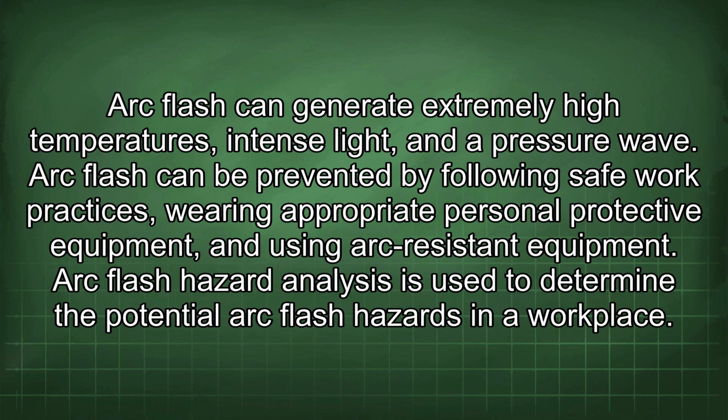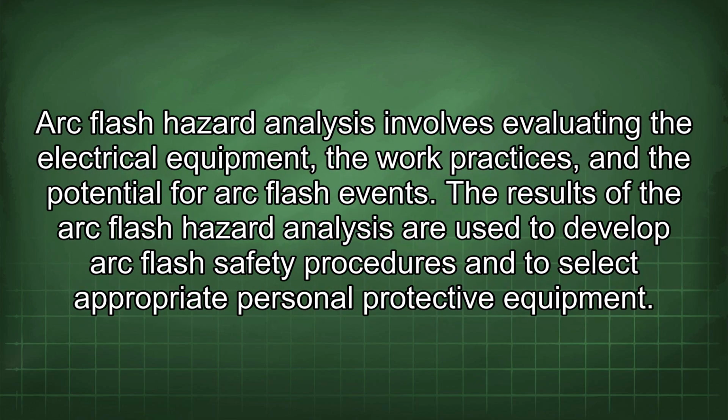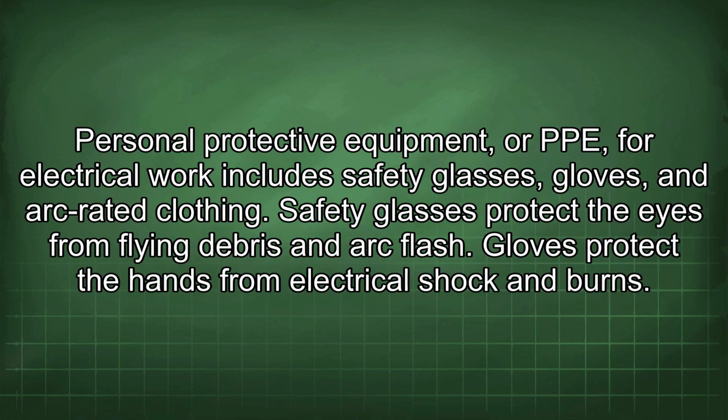Arc flash hazard analysis is used to determine the potential arc flash hazards in a workplace. It involves evaluating the electrical equipment, the work practices, and the potential for arc flash events. The results are used to develop arc flash safety procedures and to select appropriate personal protective equipment. Personal protective equipment, or PPE, for electrical work includes safety glasses, gloves, and arc-rated clothing.